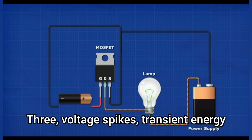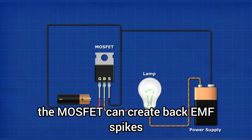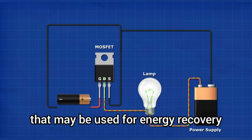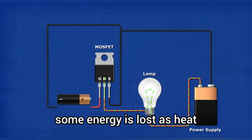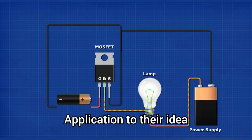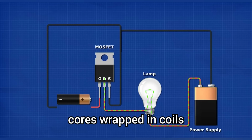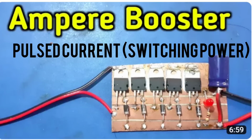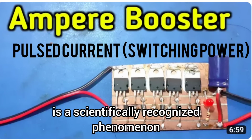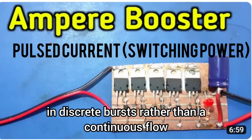3. Voltage spikes, transient energy. When switching inductive loads like coils, the MOSFET can create back EMF spikes that may be used for energy recovery. 4. Heat, power dissipation. Due to resistance and losses in switching, some energy is lost as heat. Application to their idea: if they replace the static magnets with iron cores wrapped in coils and drive them using a fast-switching MOSFET circuit, yes, the term pulsed current, sometimes called pulsed power, is a scientifically recognized phenomenon. It describes the way current is delivered in discrete bursts rather than a continuous flow.